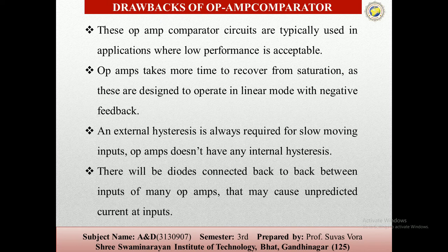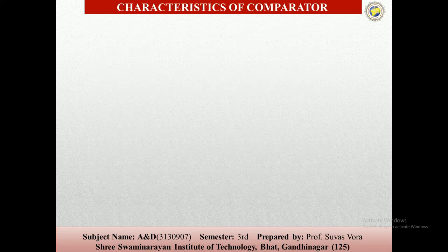Now, what are the characteristics of the comparator? The first one is accuracy. It is the smallest amount of difference voltage required at the input of the comparator to make the output change stably.